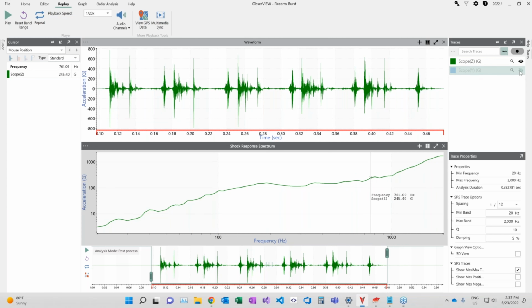So just bear with me, pretend that this scope in the Y direction is actually a second SRS recording, a completely different one, maybe of a different firearm, but I'm making one scope that's going to go on multiple weapons. So what I'll do is I'll get the SRS of these two, and I'll get the worst case.